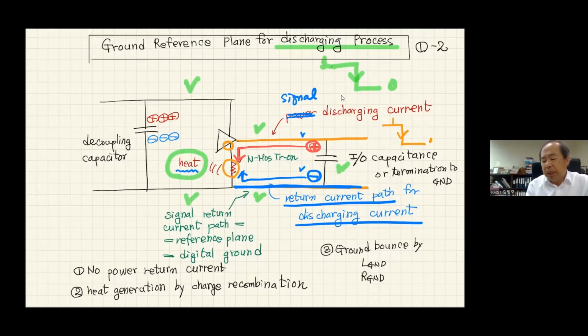And one typical part of return current design is that, especially for the case of power return current, the return current path will change depending on frequencies. As I mentioned many times in the previous classes, the power supply network will be different depending on frequency ranges. At high frequency ranges, probably the on-chip decoupling capacitor will be responsible for low impedance.